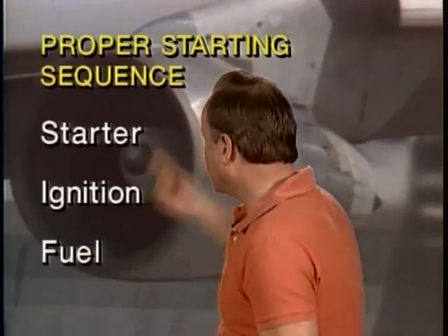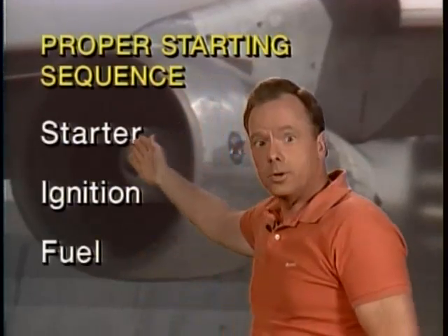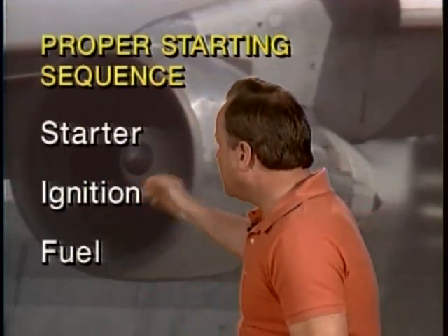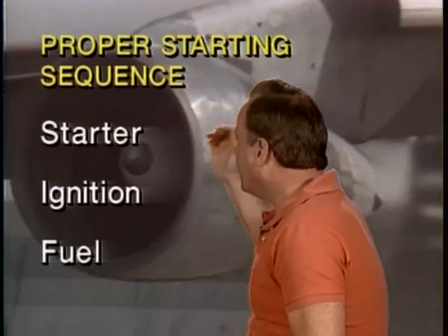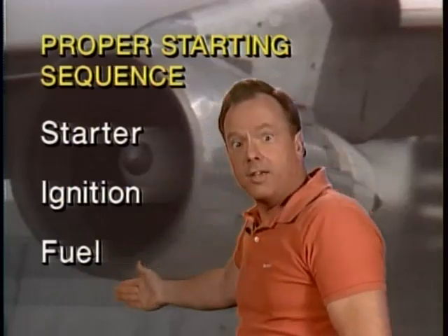Now, let you and I talk about starting a turbine engine. Maybe this is one that's already started here, I don't know. But they ask you the proper sequence for starting the engine. Well, first of all, you want to get the engine spinning. You do that with the starter motor. Then you want to make sure that you have ignition to the engine. And the very last thing you do is supply fuel to the engine.